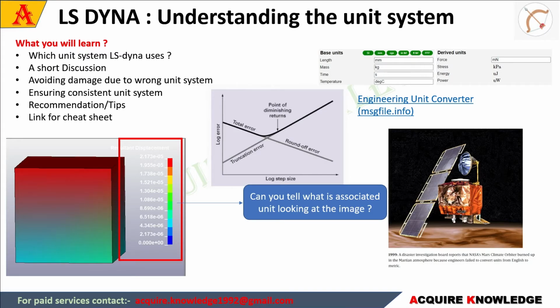In this video, we are going to discuss unit systems in finite element analysis. Even though the concept is demonstrated using the LS-DYNA tool, the core concept is the same for all FEA tools available in the market. To give a background, the unit system concept is fundamental but very crucial. Ensuring a consistent unit system is paramount while working with any FEA model.